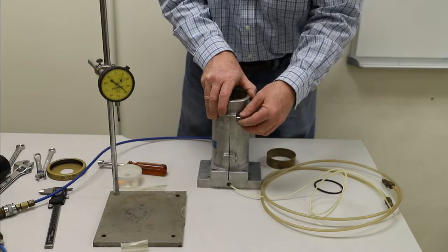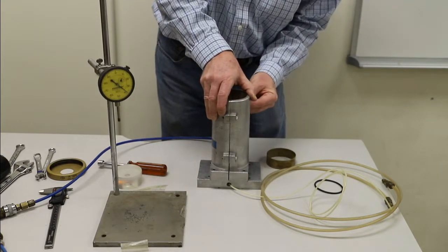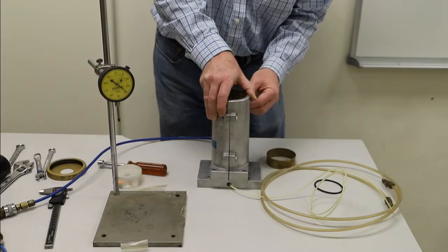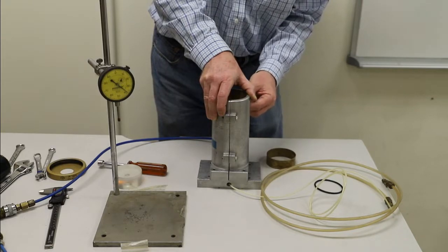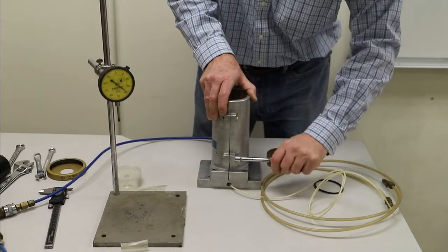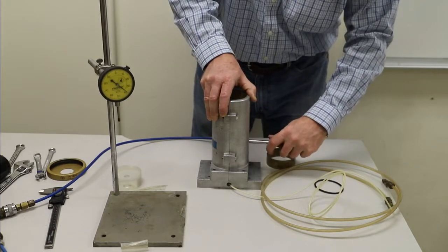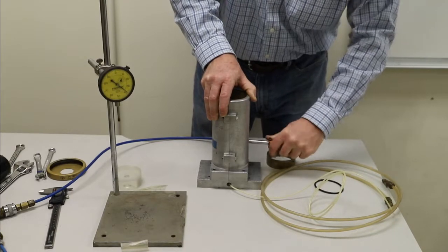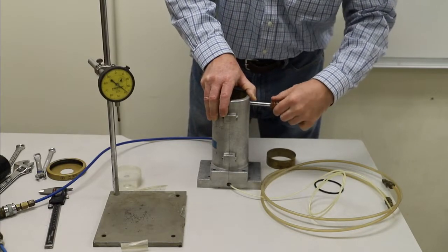So there's really two separate vacuums we're using in this experiment. One is going to be to help us build a nice cylindrical specimen. That's a vacuum on the mold, the inside of the mold. And then the actual confining stress during the experiment is also going to be applied with vacuum from a vacuum pump. I'm working in a different room, so we have a nice quiet environment for this. So I'm running a vacuum line in from across the hall.